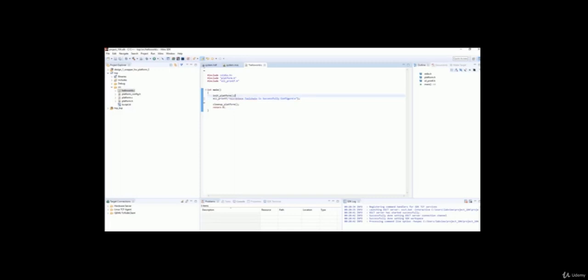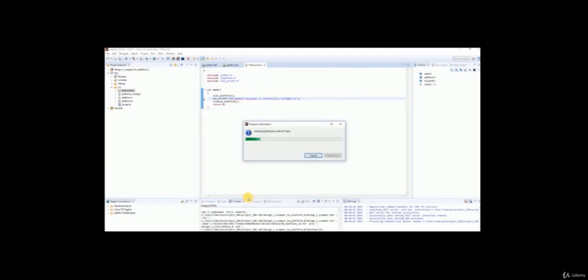Then we'll save our code, and once we save it, at the top you'll find an option to program an FPGA. Click on that option. This will generate all the necessary files and start programming the FPGA. Once FPGA configuration is successful, we are ready to run our application on the FPGA. The first thing that we always do is connect an SDK terminal. We'll go to the SDK terminal, click on the plus sign, and select the correct port. In my case it is COM15, and the baud rate we have set in this exercise is 9600. We'll select that and hit OK.